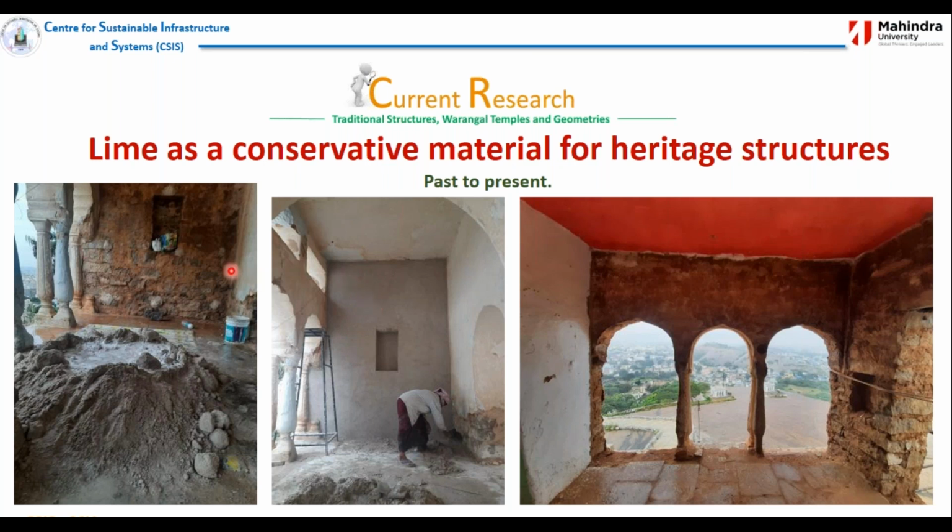Now the final coating of this has been done, and you can see the complete stones. Wherever there are voids, we had to grout by injecting the lime mortar. With lime mortar, we did not use any cement at all, completely lime mortar. Wherever loose mud was there, that was completely removed.